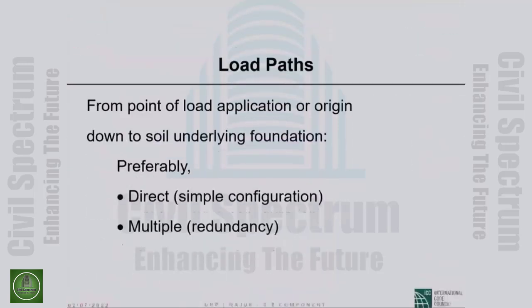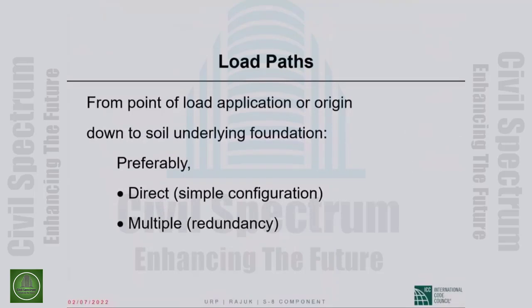So very important concept of load path. From point of load application or origin down to soil underlying foundation. It is very, very preferable in seismic design to have direct load paths, which will be provided by simple building configurations. If we have too many setbacks, projections, this and that, then the load paths are complicated, and that is to the detriment of the structure.